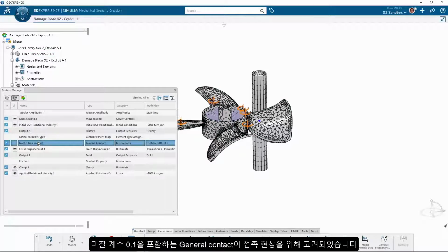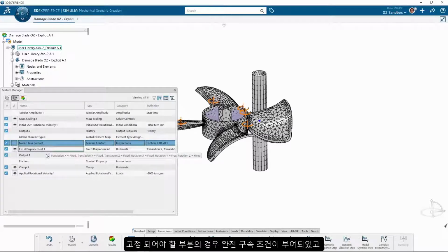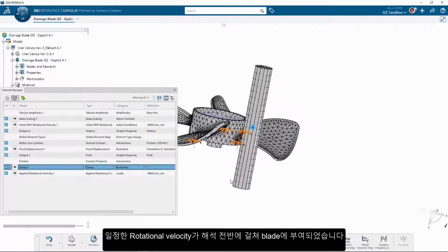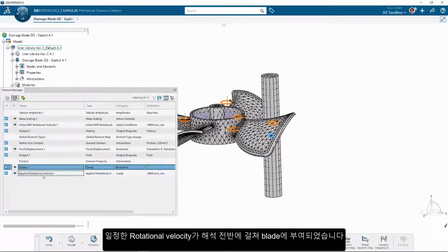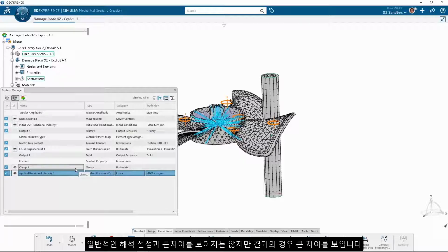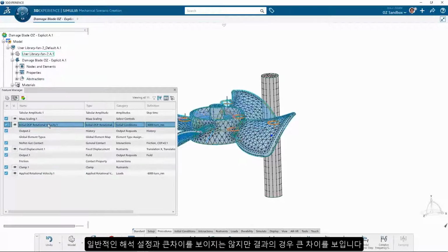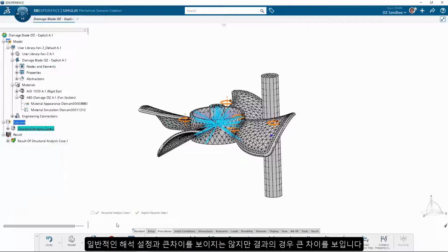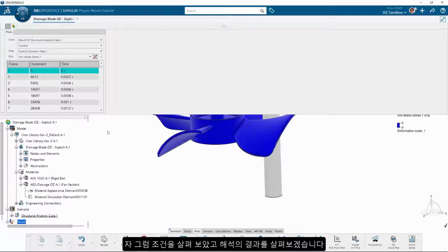Same using that no penetration contact and a friction coefficient of 0.01, and clamping the rigid body, and then just applying an initial rotational velocity as well as maintaining that rotational velocity throughout the run in this case. So, the setup for these models are not very different than when you typically would run a standard FEA problem. It's just the type of results that we can get are so much more powerful, especially for this class of problem, if this is the space that you play in, right?